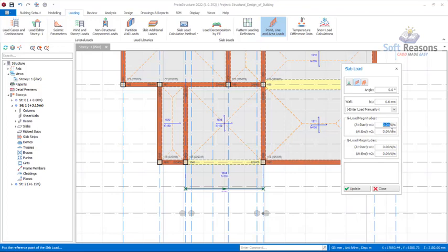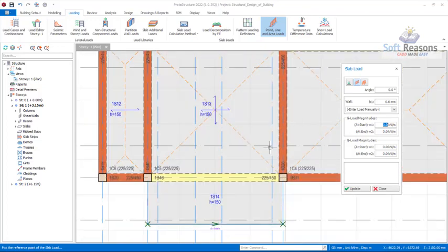So in the provisions of this G load magnitude, which is the dead load, we are going to key in the wall load, which is supposed to be 3.47. The 3.47, you have to multiply it by the height. When you multiply it by the height, you will now get the total load that is running along that length. So 3.47, the height we are considering is 2.9, because we are to convert everything to meters.